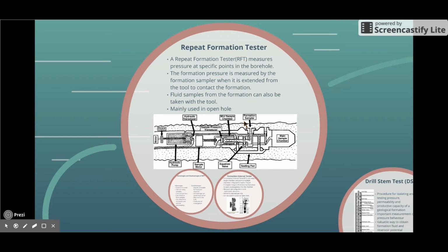A tool is run down into the hole to get a continuous digital readout of the hydrostatic pressure. At any point, a rubber pad is hydraulically forced into the wall of the hole. A tube at the center of the pad is then forced against the formation. This will create a low pressure area and force the fluid into the chambers.